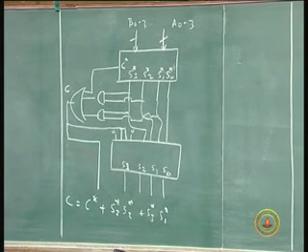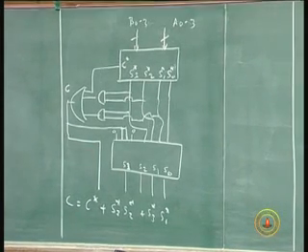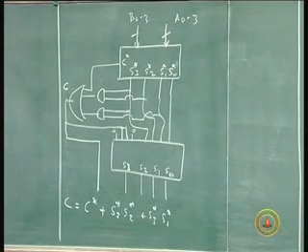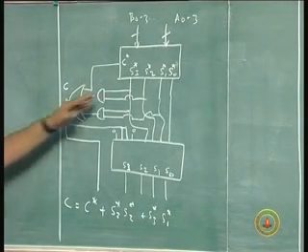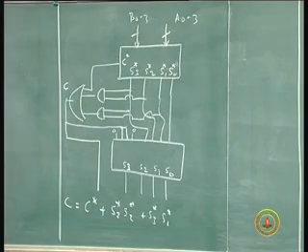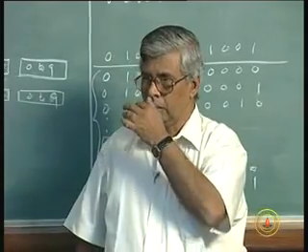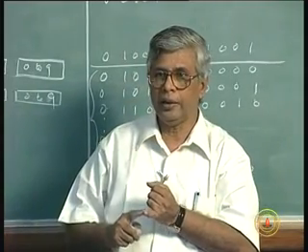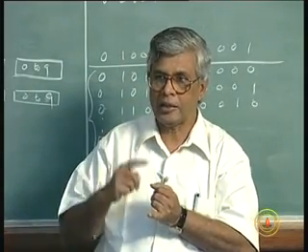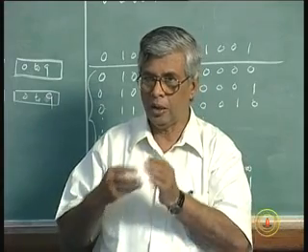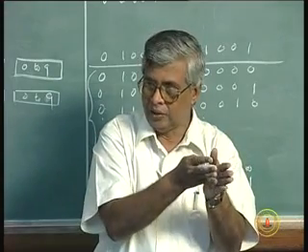The entire addition, whenever I need to add 6 to the original sum, I have to add 6 to the sum when the sum exceeds 9. As soon as the sum exceeds 9, I have to have a carry addition of 6, which means I already get into my second digit.